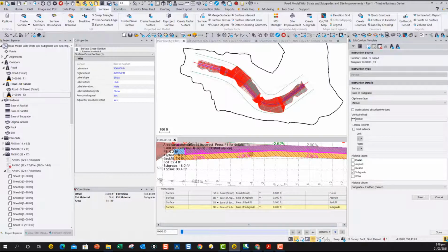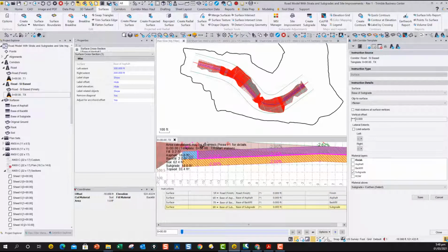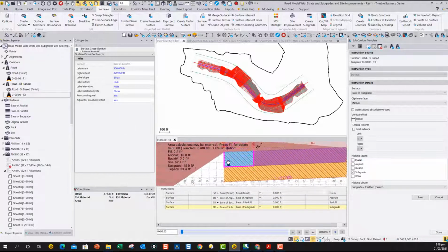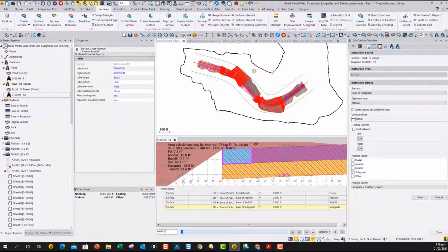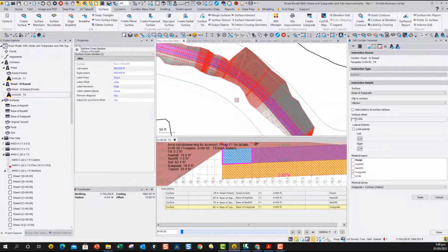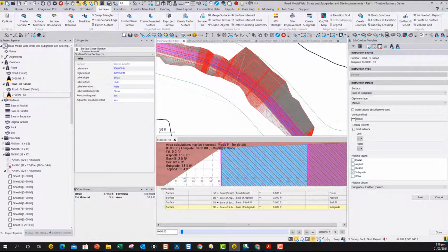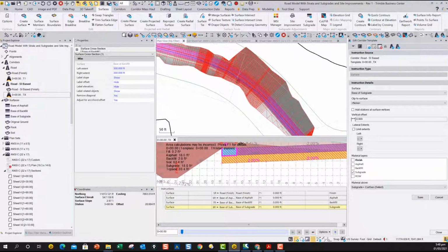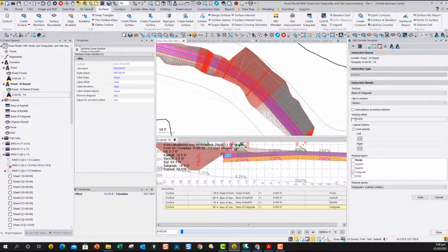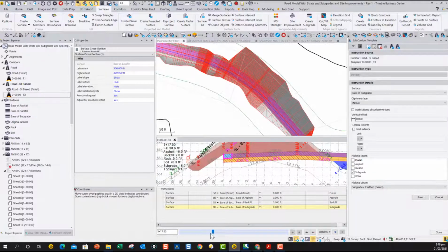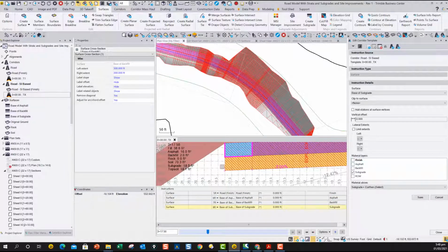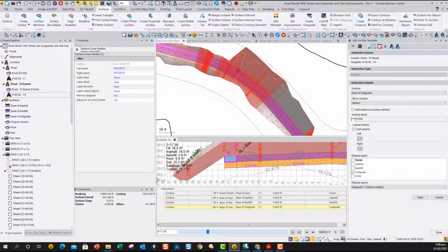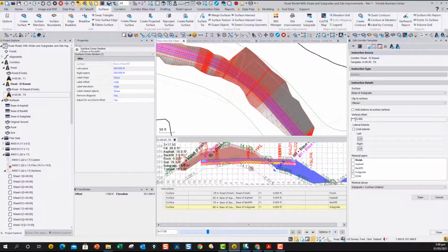And these are coming up because they're referenced to the corridor, so I can select them and do this referencing here, and in this case did the same thing for these. And all that does is it basically means when you're on a curve, when you're cutting chords through the model, if you slice it, then this point wouldn't be in exactly the right location. So this adjustment basically looks at the curvature of the road, looks at the offset of this point, and makes an adjustment based on the arc to chord, so this is actually correct at whatever station I stop at. If I don't do that, then what you can see is these don't exactly match when you're in the chord section. So it's a minor defect, but this allows you to correct for it if you want to.